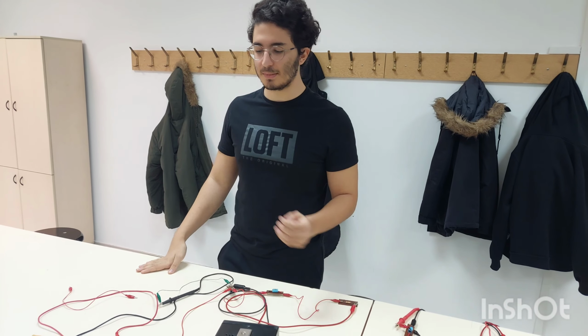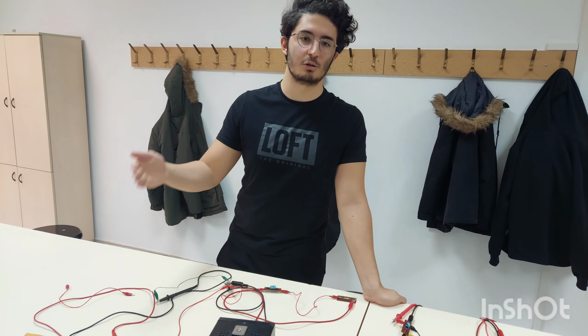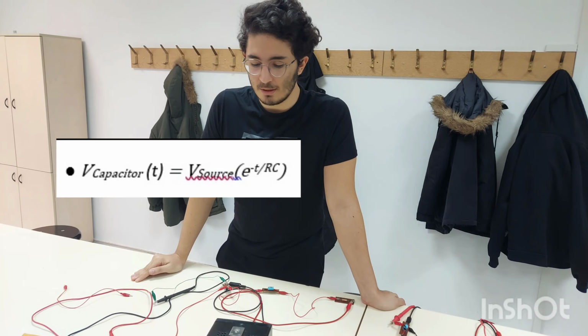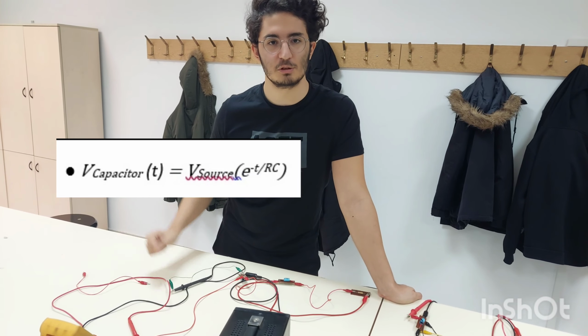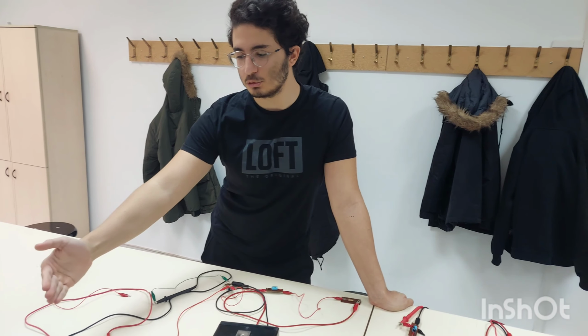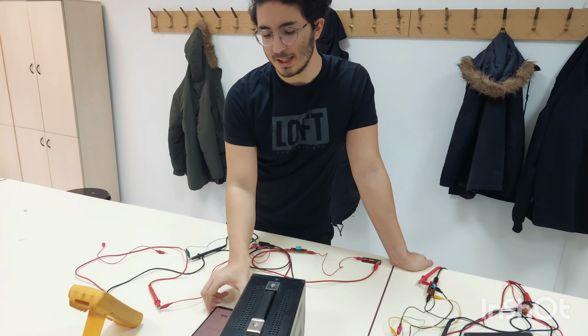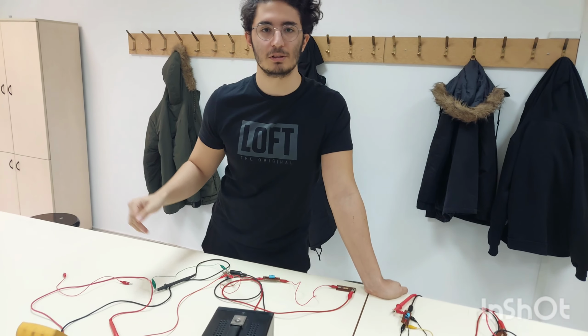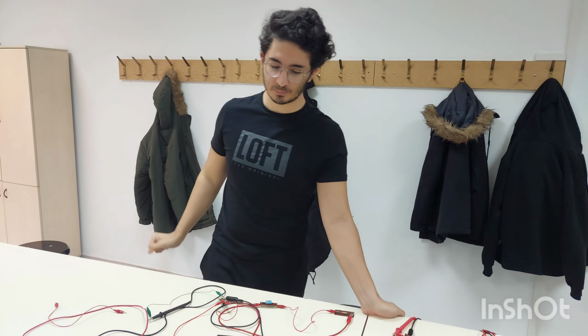After charging them and getting them to the initial voltage, we will disconnect the terminals of the capacitor and they will undergo a discharging process. While they are discharging, the voltage across the plates of the capacitor will drop. When this value drops to half of its initial value, I will stop the chronometer here, and these values will be recorded as experimental half-life time values into table 1 and table 2.